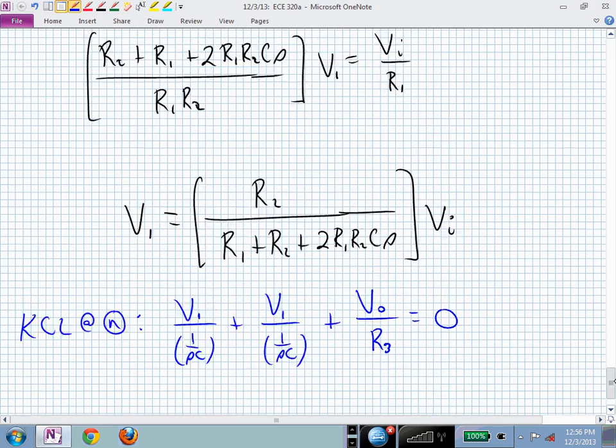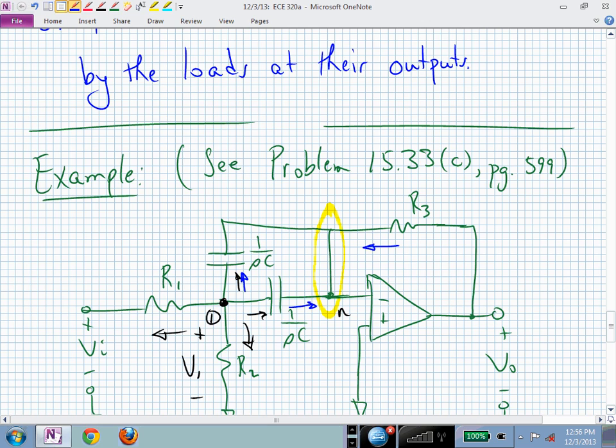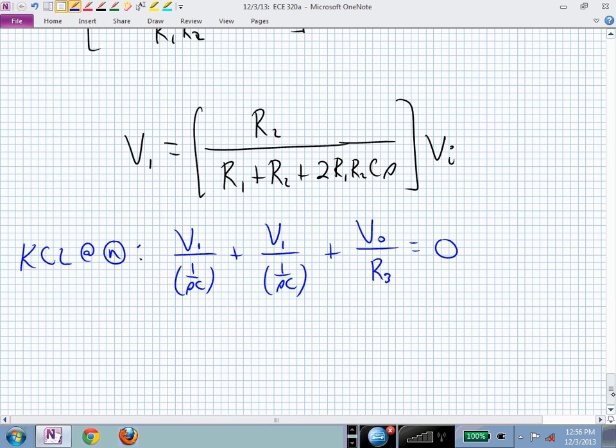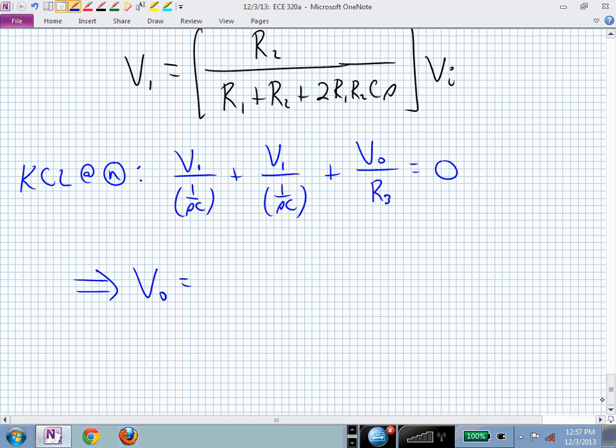So now I've directed all of those blue currents into the node. So I'm summing all these algebraically the same. They're all going in, so I can just say I'm going to call all of those positive on one side of my equation. Is that okay? I'm going to get a negative when I solve for V1 towards the output V out. If I now write V out in terms of V1, I now have VO is equal to, all those SCs come upstairs, and I have 2 of those, plus I get that R3 moving through, so I now have minus 2 R sub 3 CS times V1.